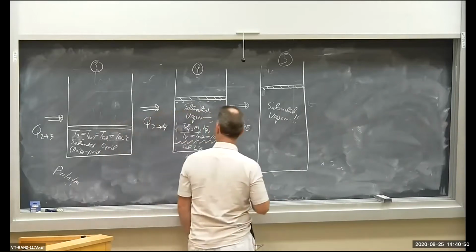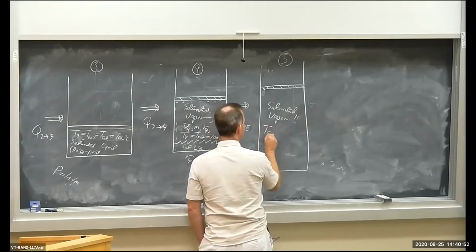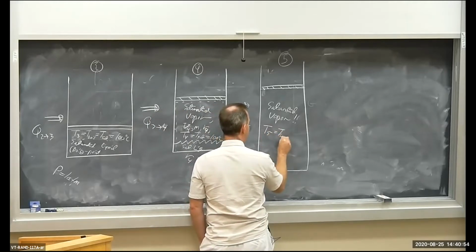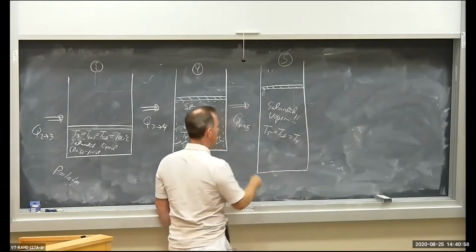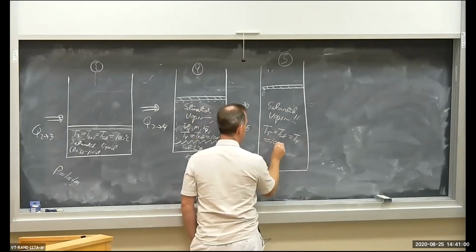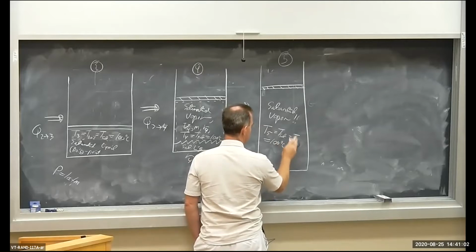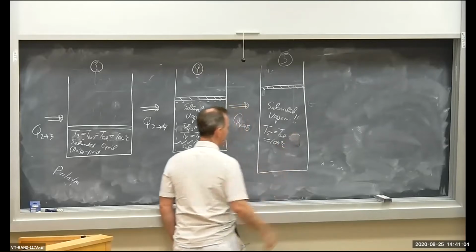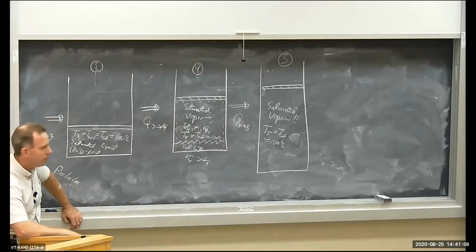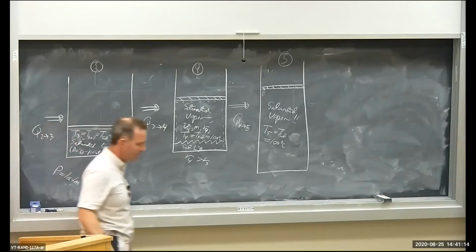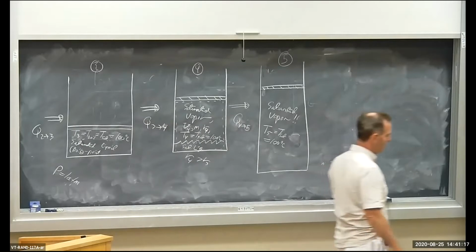So that means temperature is the same. T5 is equal to T sat. So that was T4, T3, and that was 100 degrees centigrade. I'm just going to get rid of that T4. So T5 is still equal to T sat, which is still 100 degrees C. T sat, or the saturation temperature, is a fancy name for the boiling temperature.